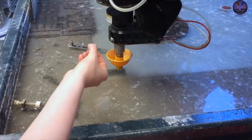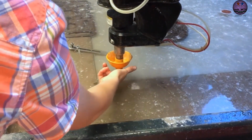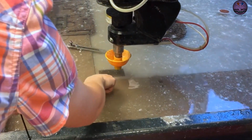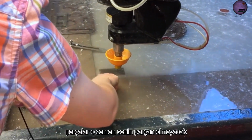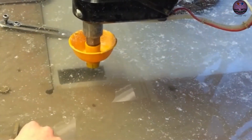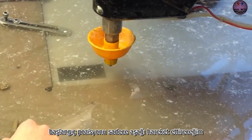Because these are higher than your cutting surface, there's a risk that the nozzle will break. You also want to not interfere with any existing cut-out pieces, or your part will not be the right shape at all. So using the arrow keys, I'll move the nozzle over to a good starting position.